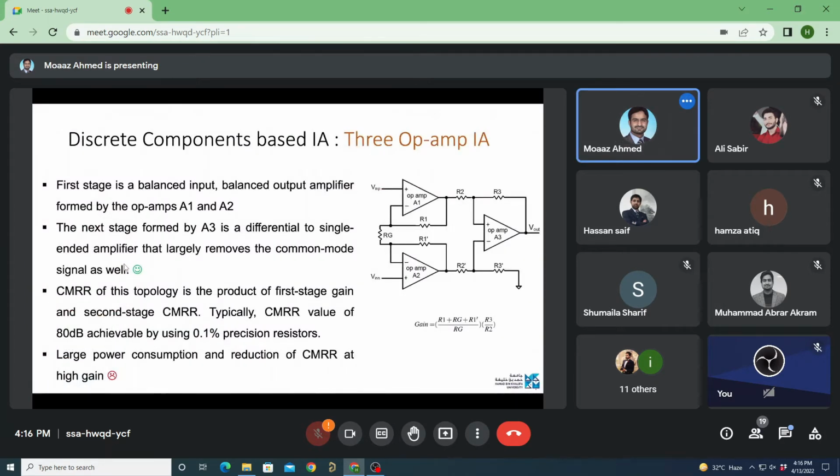So here we have a kind of 2-stage amplifier scheme. We are using 3 discrete op-amps. Amplifiers A1 and A2 form a balanced input stage, followed by amplifier A3, which is the output stage. The inputs V in P and V in N see the differential pair of amplifiers A1 and A2, which in CMOS would have infinite input impedance. So again, the sensor loading is avoided.